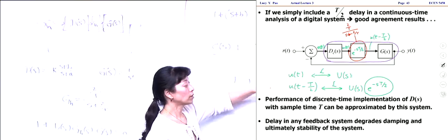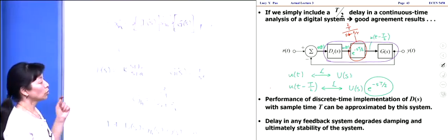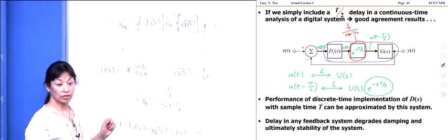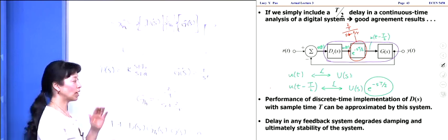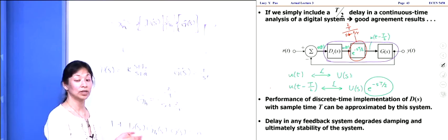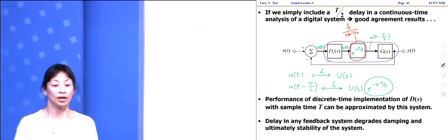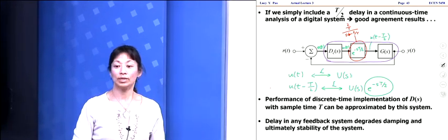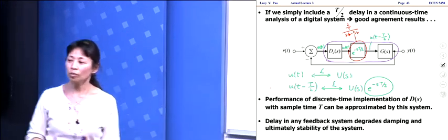One requirement for the standard root locus techniques is the numerator polynomial has to be of order no greater than the order of the denominator polynomial. So depending on how things work out, you might have to plot as a function of 1 over T if that doesn't work out, right? So that's why I said you want to plot it either as a function of T or as a function of 1 over T. Either way, you'll be able to back out where the poles are as a function of T itself. Right, does that help?